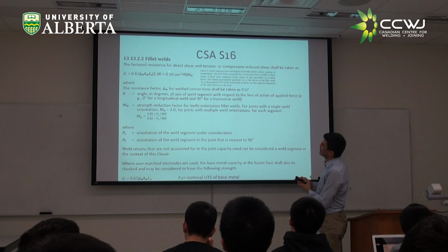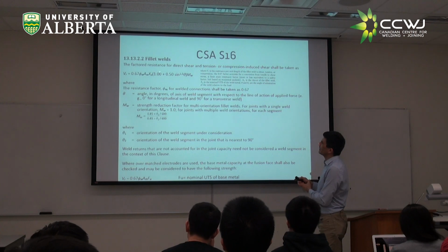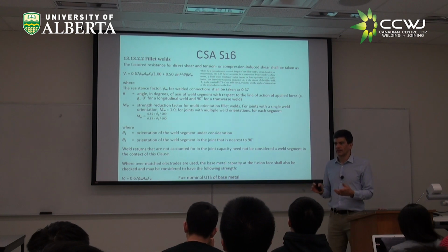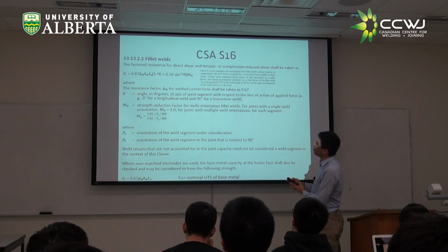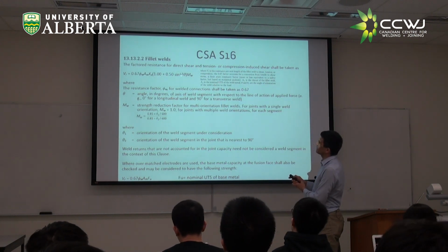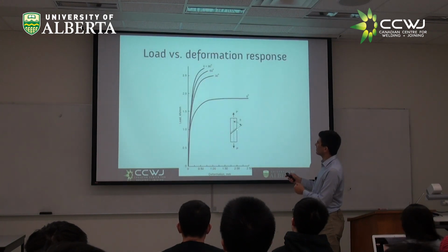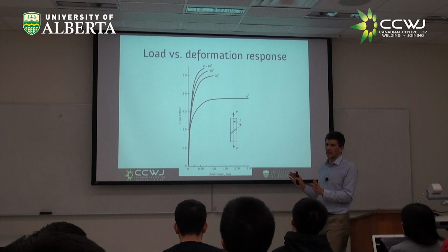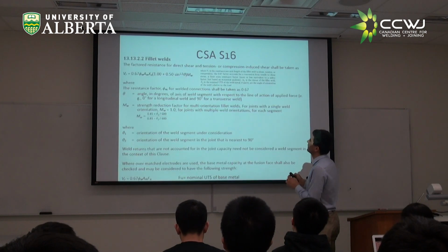Now, then we have this thing here. This part here is something that typically is not in the way you calculate weld lengths in the US. And I need to learn more, but I don't see this in the American literature. What here it says 1 plus 0.5 sine of something. This theta is this theta here, okay? So if the weld is longitudinal, what is theta? 0, right? Okay. If theta is 0, sine of 0, how much is that?